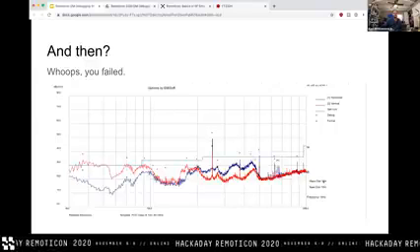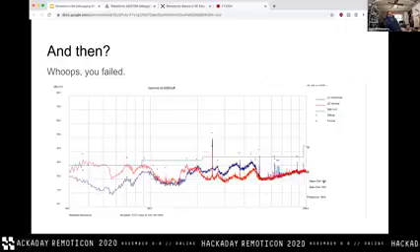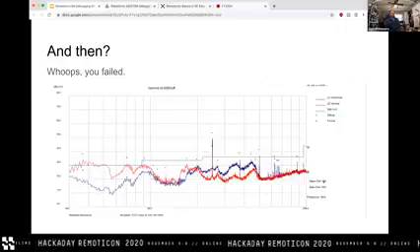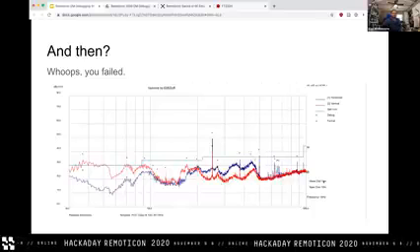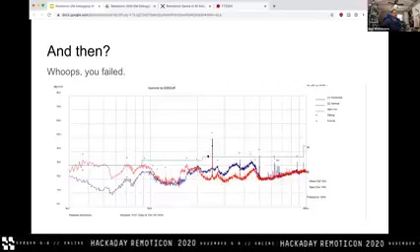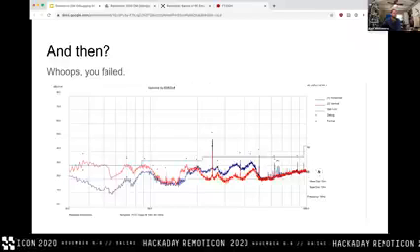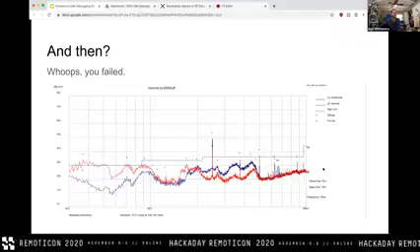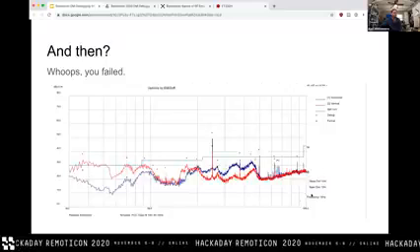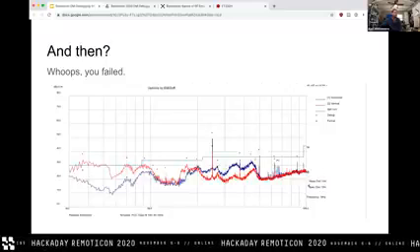So basically the receive antenna is 10 meters away from our product while they're spinning it around on that table, which mostly just means that this is the limit line we choose. There's also a testing regime at 3 meters with a slightly higher limit line. But as far as I'm aware, most people use 10 meters for this certification.